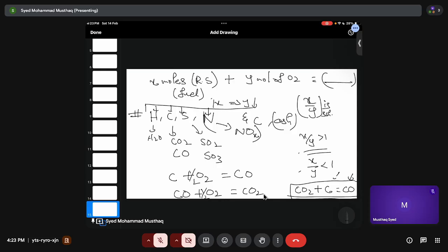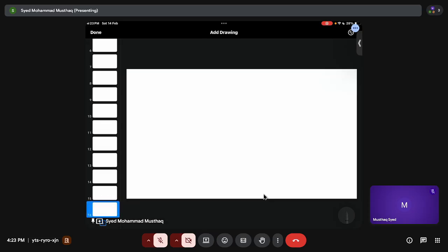This is about the gases. For solid fuels you need to have a fine surface area, because you are reacting with oxygen. So you need more and more surface area to air ratio. That's why you need fine solid fuels. But in liquid fuels, what you can do to increase surface area is disperse them by doing atomization.